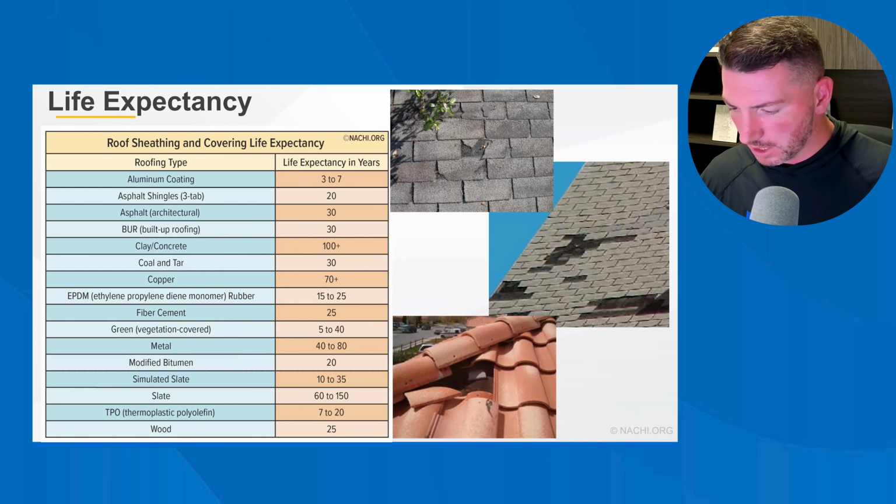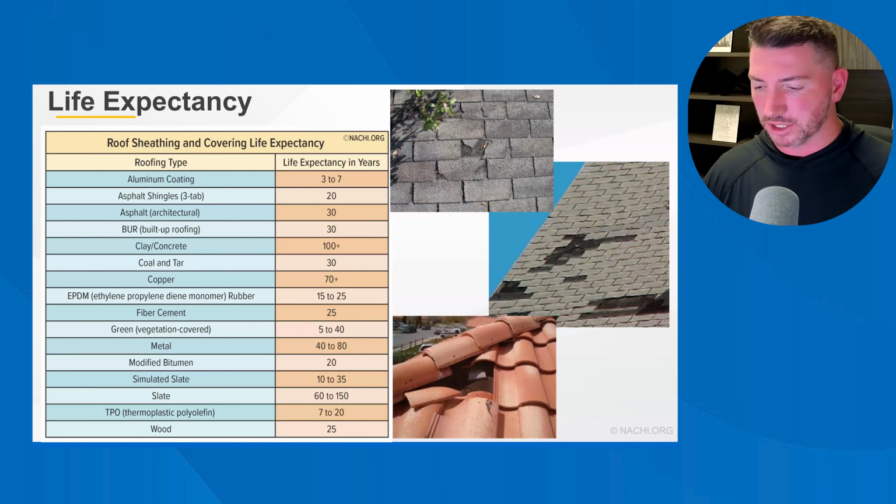So, the inspection image, roof damage caused by an overhanging tree branch, like we said. Environmental conditions. This category of rapid deterioration on the roof covering can be attributed to airborne pollutants that are prevalent in industrial areas, as well as from the acidity of pine needles breaking down the roof surface. Chemicals definitely do different reactions with asphalt composition shingles.